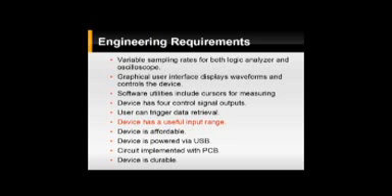The input range could be as high as 60 volts with minor hardware replacements. The device must be affordable for students, costing no more than $300. And it also must be solely powered via the USB on any typical computer, thus requiring a maximum current draw